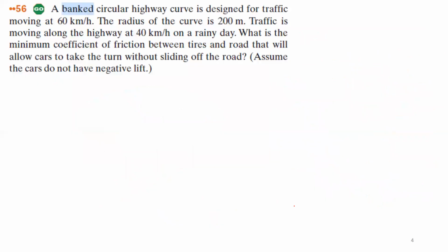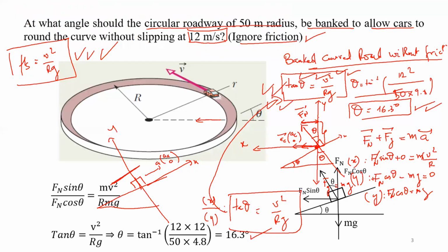Now, let me make it more difficult and look at the most general problem. Again, here, this Vmax is a V design of my banked road. So when I design the banked road, I look at the worst case scenario, which is there is no friction. A slippery road, you know, icy, friction is equal to 0, but still, if I respect the maximum speed here, I will not slide and I will not slip. I will not have an accident, okay, if I respect the maximum speed.